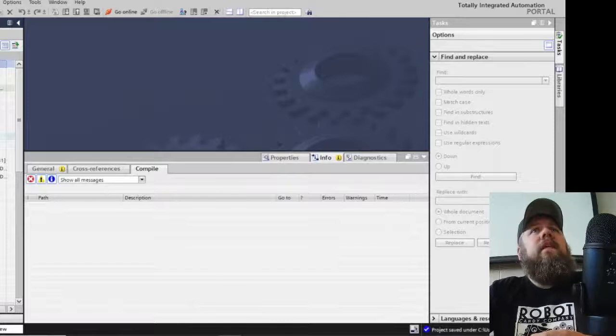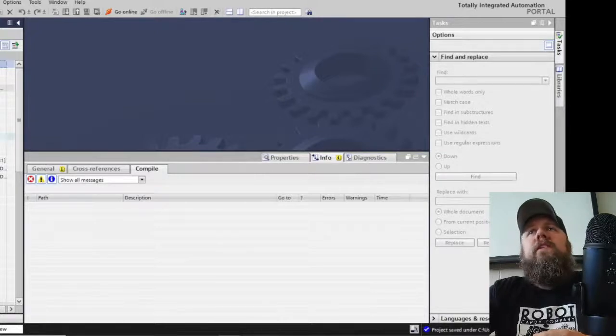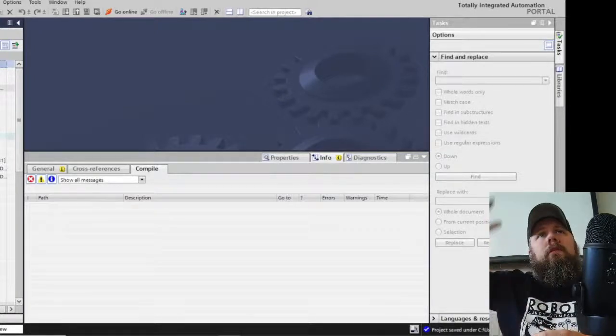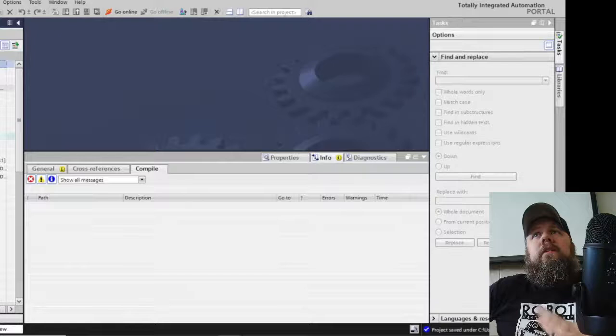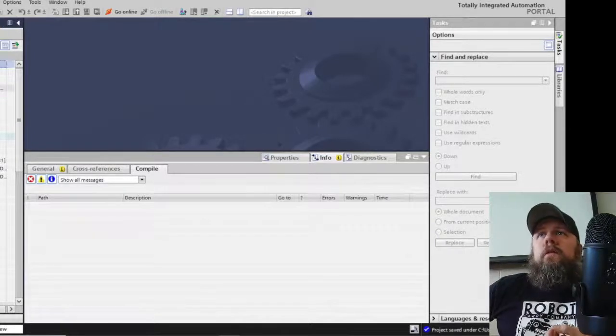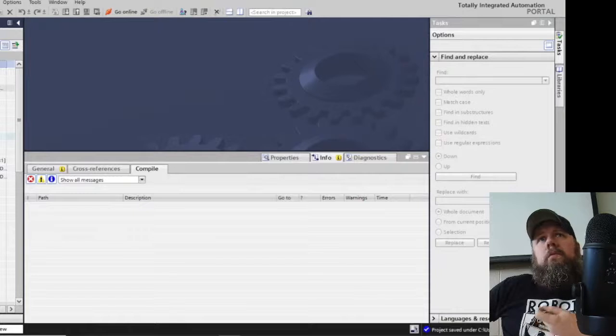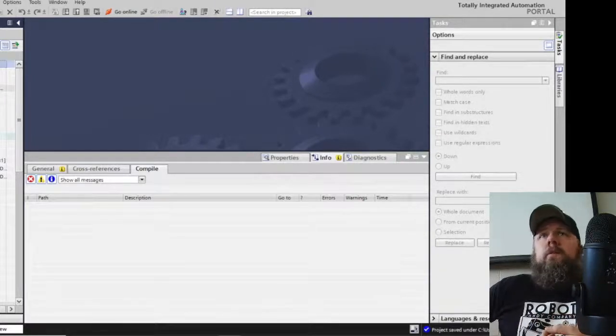Okay. So let's say that we do have that waveguide. You plug it in, it'd read that way. Or if instead of using the waveguide, I had y'all use a little laser sensor, the laser sensor doesn't talk in 4 to 20 milliamps. It talks in what's called I2C, which is a little serial communication protocol. Well, the PLC doesn't talk in that. So we'll use that little microprocessor to convert that into something the PLC can read.